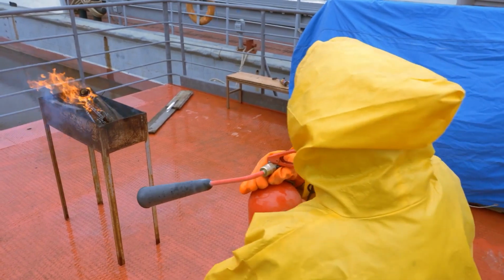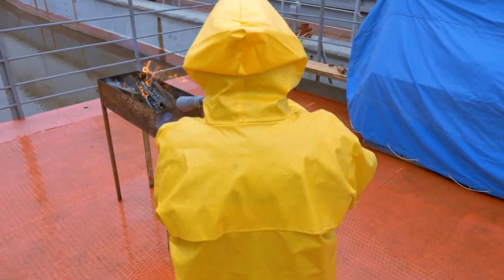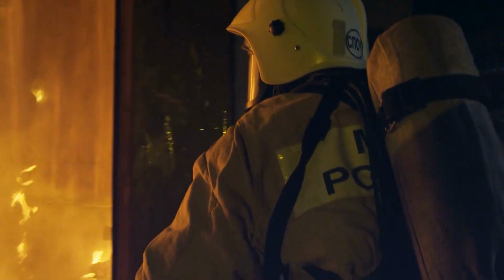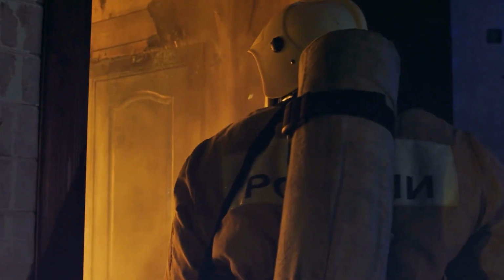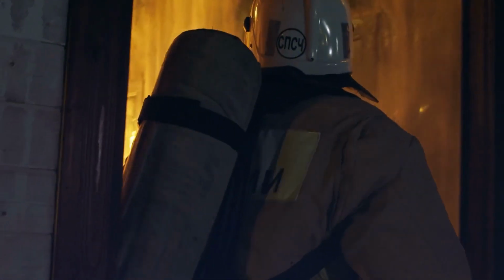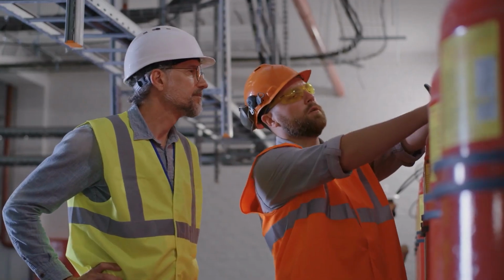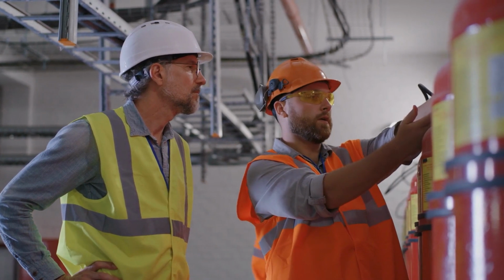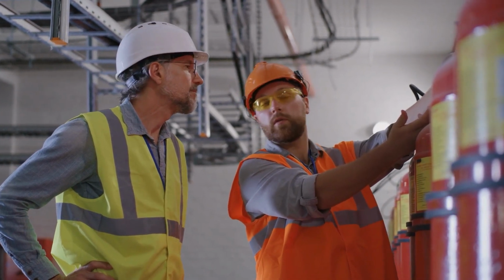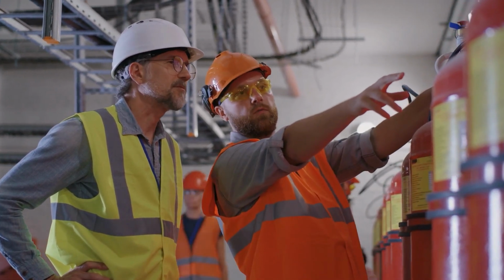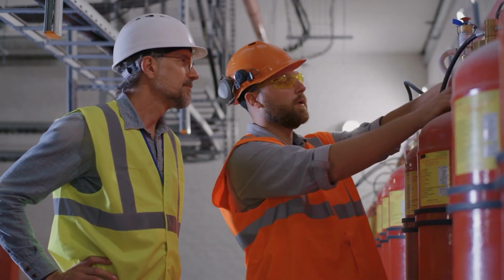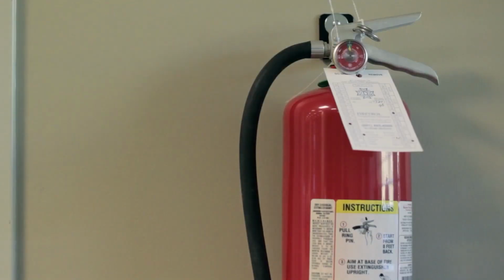Beyond training, a licensed fire extinguisher service vendor must service extinguishers annually. In addition to annual service, in-house inspections must occur monthly, including verification that annual service and inspection has occurred, ensuring the fire extinguishers are in their proper locations, and also ensuring that they are ready for use by being fully charged and readily accessible. Not all extinguishers are appropriate for every fire emergency.